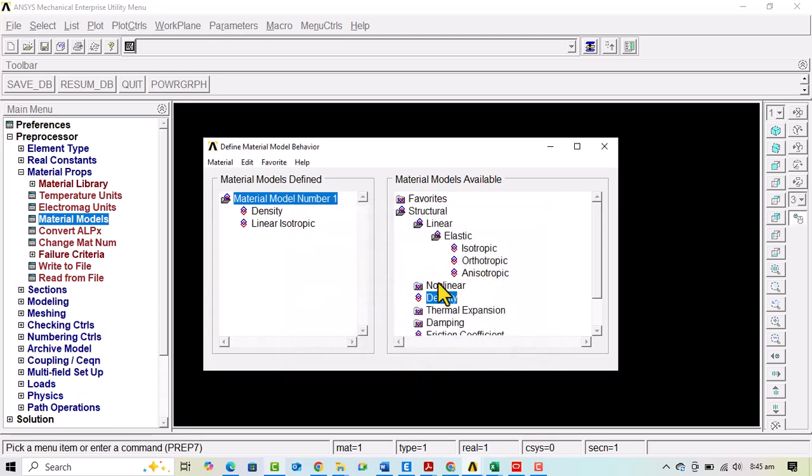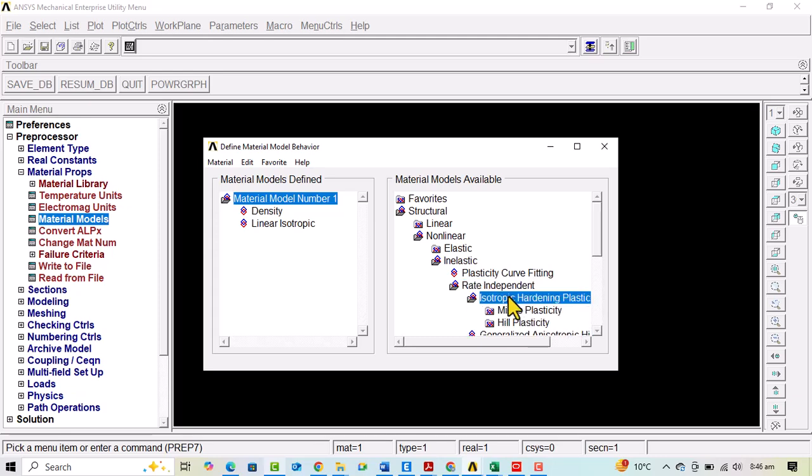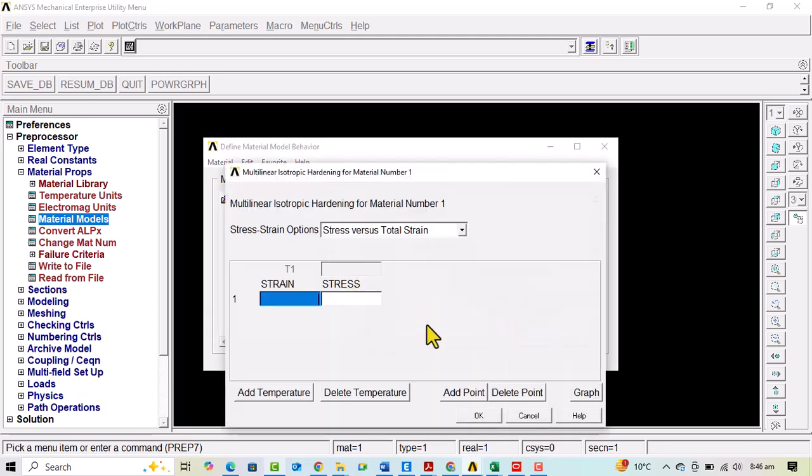After that I would also be defining an inelastic material model as well. These are the data which were obtained by experiments. I will be defining these 4 points. This is the value of the stress strain curve which we obtained by loading a brick. So this is experimental data we use to model our bricks.